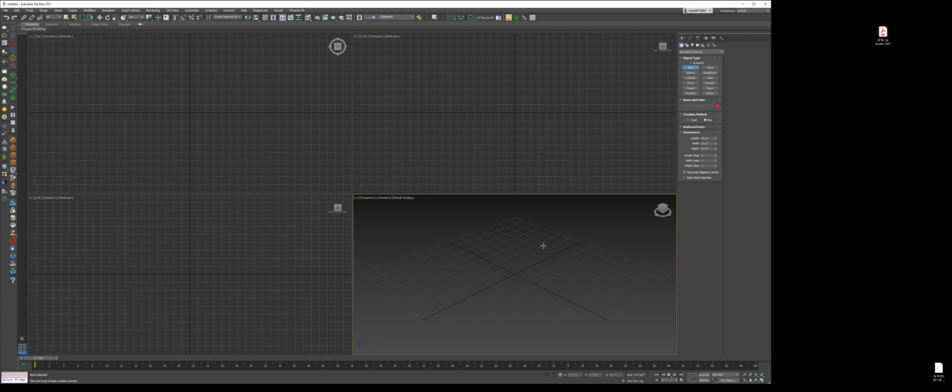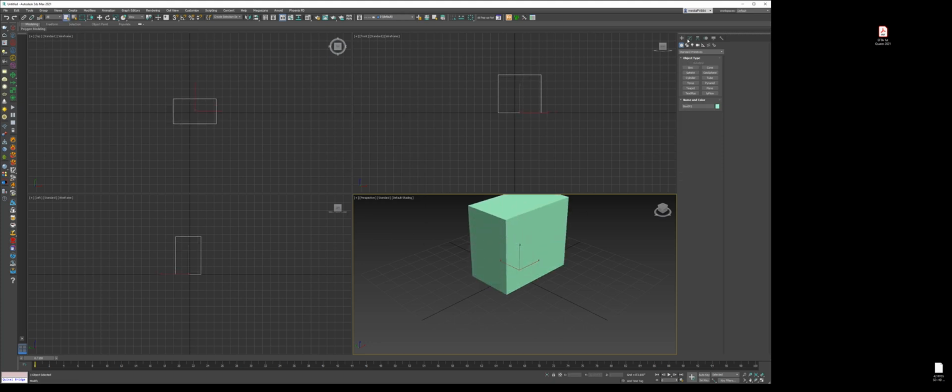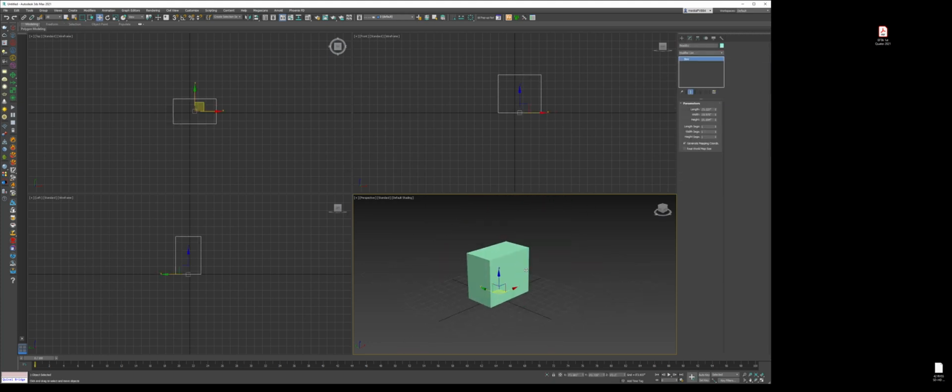And then now if you were to create a box, again, the trick is to work in true scale. So everything you always want to do, you want to keep it true scale. So if I do 7 feet, there we go. So that's 7 feet tall. So 18 inches for a wheel, 20 inches. Everything works perfectly if you keep it true scale. So that's the first thing that I do.